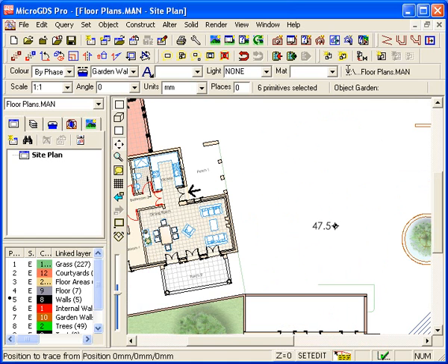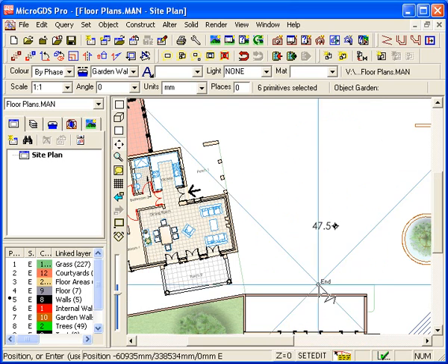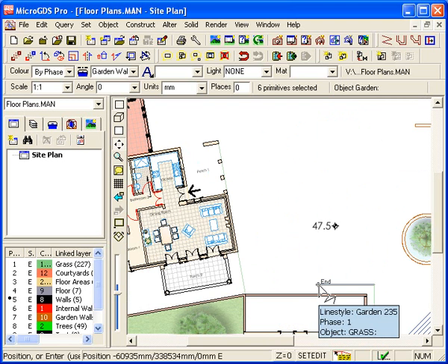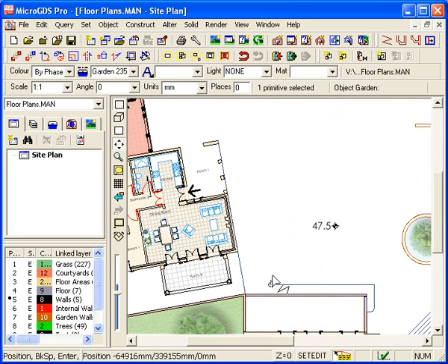Now let's complete this grass area here. Using the line command, I'm going to start here and press the Shift key because I want to extend this existing open line, and use the horizontal guide and click a point about here. I now want the line to be parallel with this one. So all I have to do is hover over here and a parallel guide is created. And to finish, hover here to get an extension line. Where the parallel and extension lines intersect, I can click a point snap and press Ctrl and Enter to close.